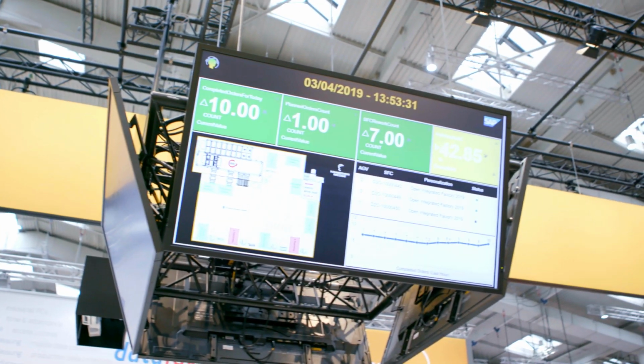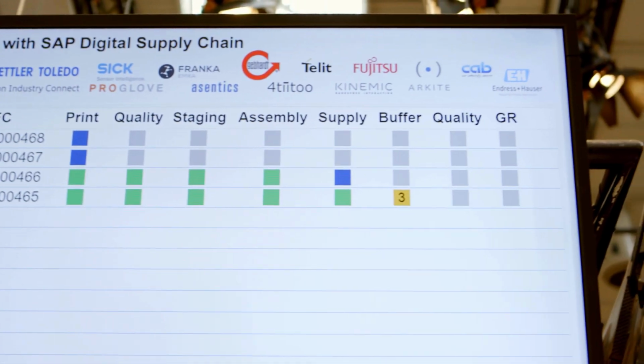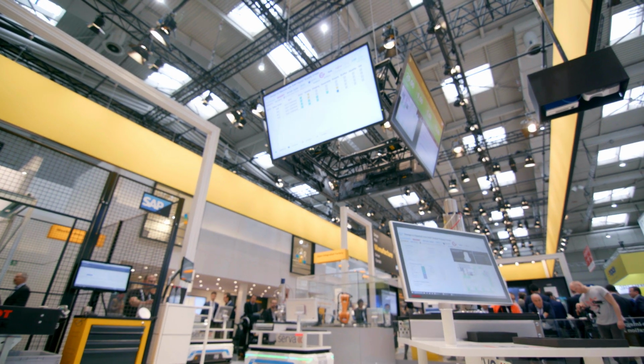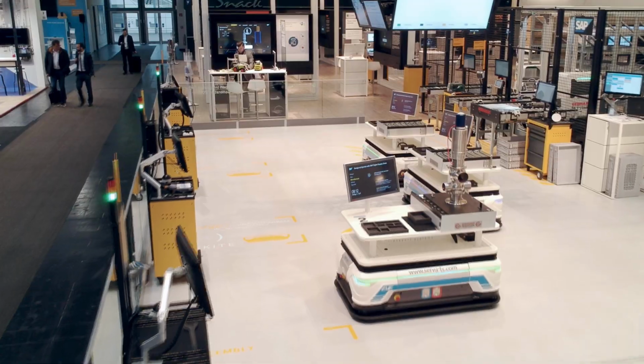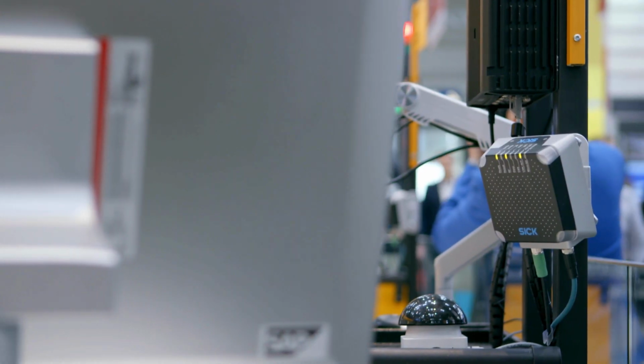We use the colorful bouquet of SAP technologies. For example, SAP Plant Connectivity is the software layer, which talks in the direction of automation using OPC UA as the communication architecture, and also takes over orchestration, saying, for example, when vehicle arrived occurs, then activate the RFID reader to read the tags.